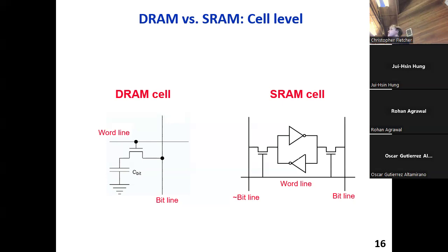As it turns out, modern SRAMs actually do, however, precharge the bit lines. They precharge the bit lines to the same, usually VDD over 2, neutral value that we precharged the DRAM bit lines to, but not because it's fundamental. They do it to decrease their read time. If you precharge to VDD over 2, you can more quickly adjust the bit lines on the next read to whatever value you need. And so your access latency for the next read is reduced, but it's not needed fundamentally.